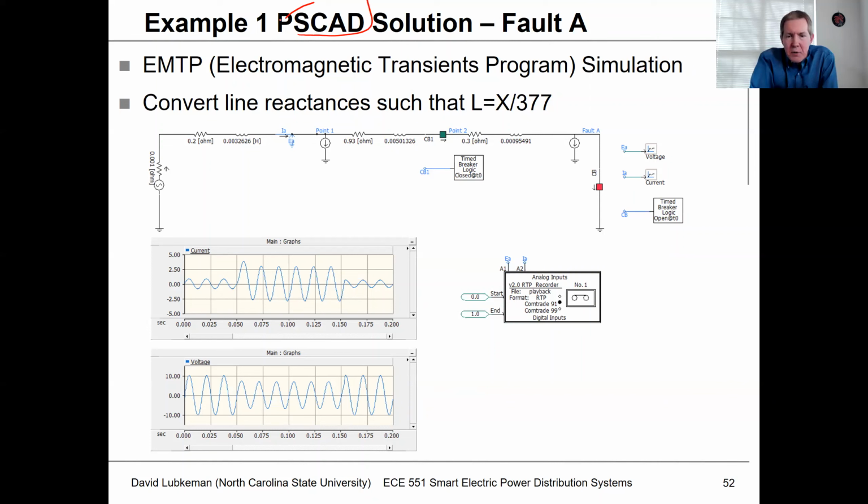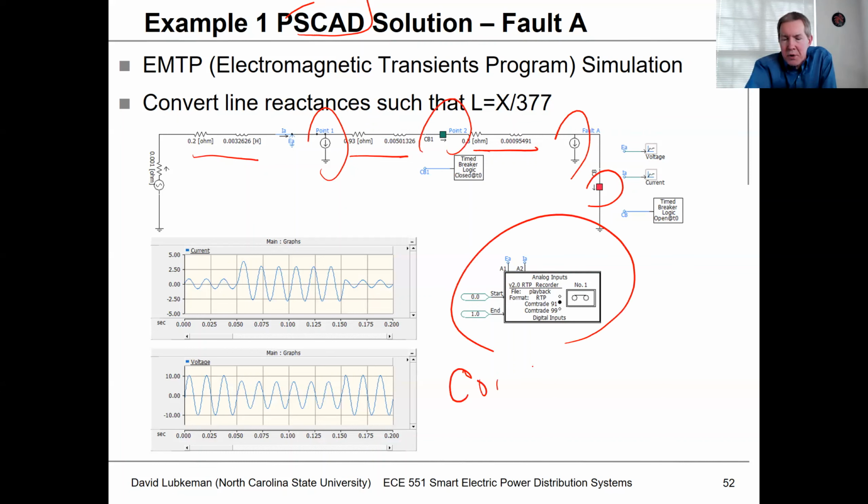Simscape. But what I'm doing in this case is I'm basically mapping these impedances into an impedance model. And what I'm also doing, just so I could show the loads, is I'm putting some current devices in here basically to look like constant current loads. And then I'm putting these switches in here so I can model the response to the fault. Another thing I'm doing in this case, I'm putting in a ComTrade recorder so I could actually create a ComTrade file from this that I showed you in the previous example, in the previous section of the lecture.